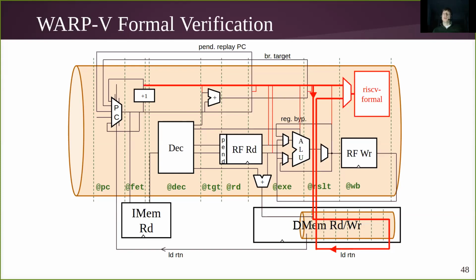So for each instruction that retires in our CPU, we need to feed that instruction into the checks. So all the relevant fields of the instruction: the PC, the actual instruction in its binary form, the register values that it's operating on, the resulting register value written back to which destination register. So all these fields need to be presented in the same cycle to the checking.